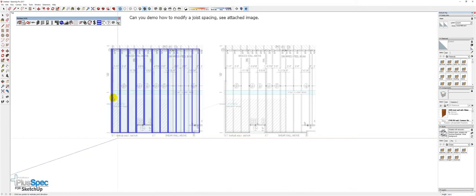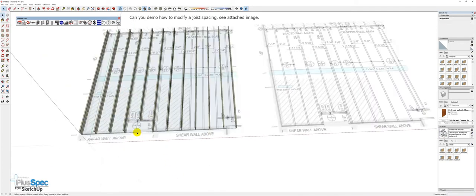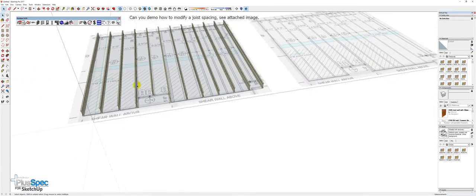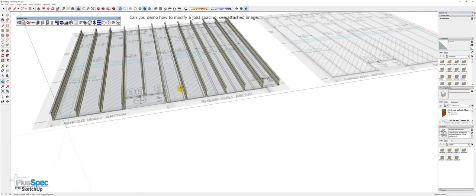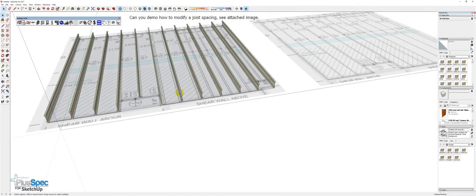direction. This is one way, okay? Now you might want to specify that your joist spacing starts from left to right instead of right to left. Let's have a look at what happened. Okay, it automatically just did, and this is what you would do at feasibility study stage. Is that, we don't know where the joist spacing are. Engineer hasn't got involved. We'll just go and put in our joists according to what the standard spacing would be